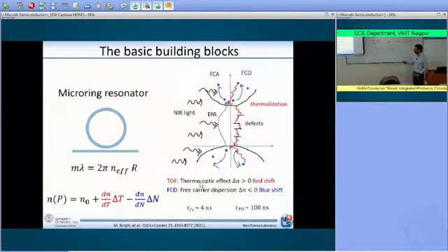And the reason why the refractive index changes is because the free carriers here thermalize, and so we have an increase in the refractive index. But at the same time, the free carriers do affect the refractive index, and therefore we also have what is called free carrier dispersion, meaning a change of the refractive index caused by the free carriers.